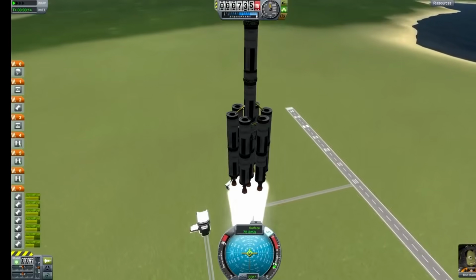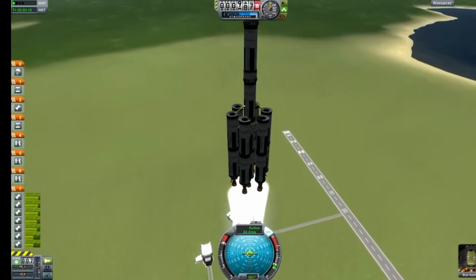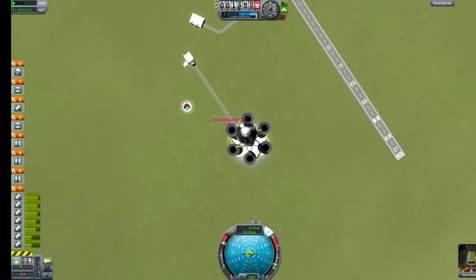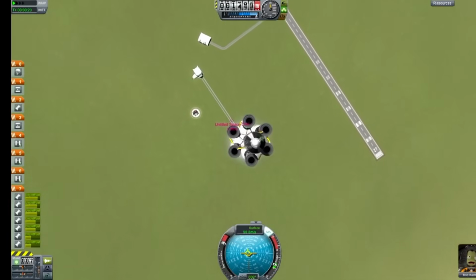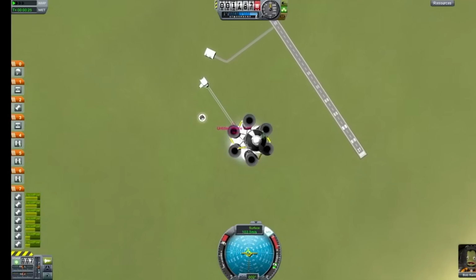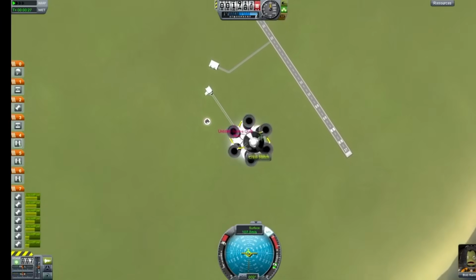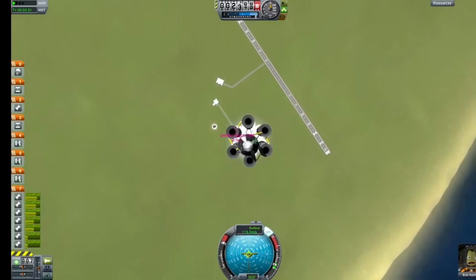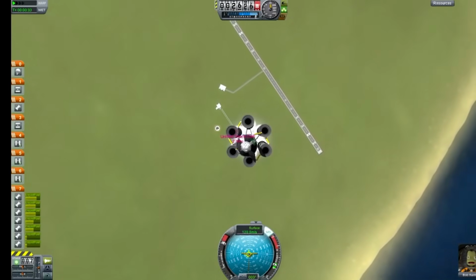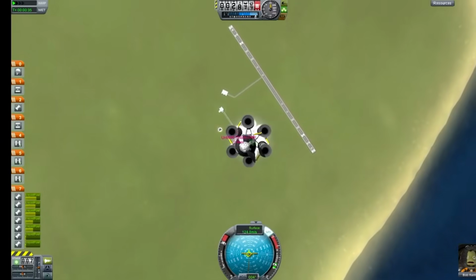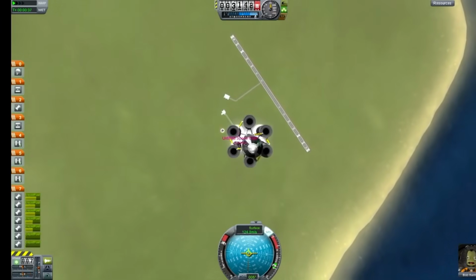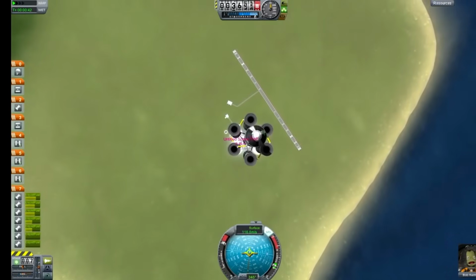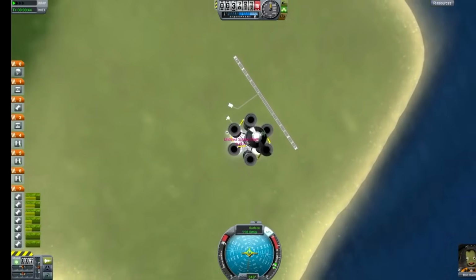And this is much more efficient in terms of mass because you're basically not carrying all that extra tankage on that core. And this is something which is very easy to do in Kerbal Space Program. So people don't do it with just 2 boosters, they do it with layers and layers of boosters to get the maximum performance possible. But in real life, it's very difficult to take that fuel crossfeed and feed it into that propulsion system without messing things up. And nobody's ever really managed to get that.